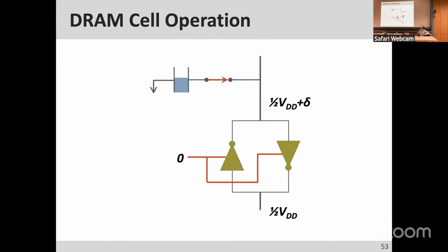And at some point, the sense amplifier gets enabled. This happens when you do an activation command. You activate, and activation enables that word line to enable the access transistor. And after some point, some charge gets shared with the bit line, and the bit line charge gets perturbed. And after some point, some circuitry enables the sense amplifier so that that perturbation is amplified. That's the sense amplification, to VDD on top and 0 at the bottom. This is how you actually get sensing.